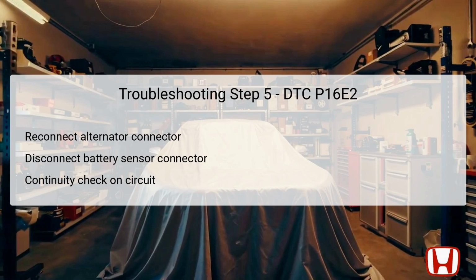The next essential task is checking for continuity between the test points on the battery sensor while the vehicle remains in the off-lock mode. The aim here is to verify whether continuity exists between the test points, indicative of a sound connection. If continuity is confirmed, the alternator itself likely needs replacing, as it is no longer performing its required function effectively. If there's no continuity detected, the troubleshooting should progress to analyze potential faults in the wiring further upstream.